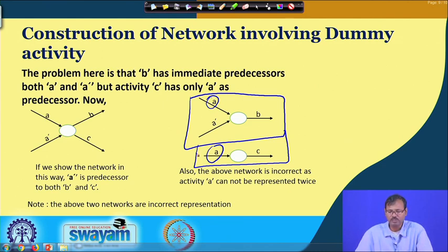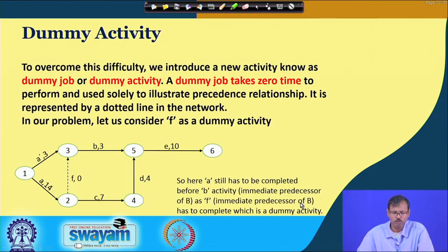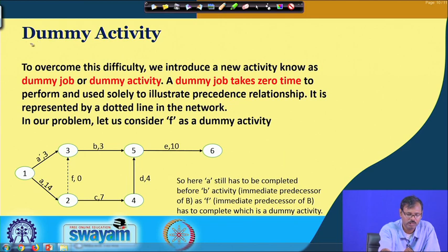So, basically if one precedence is required for a number of successive jobs, that is not very easy to depict in a network, or you can say in the arrow diagram. That is a critical condition in the construction of a network. So, to avoid that criticality or to address that problem, a new concept has come, that is called a dummy job.